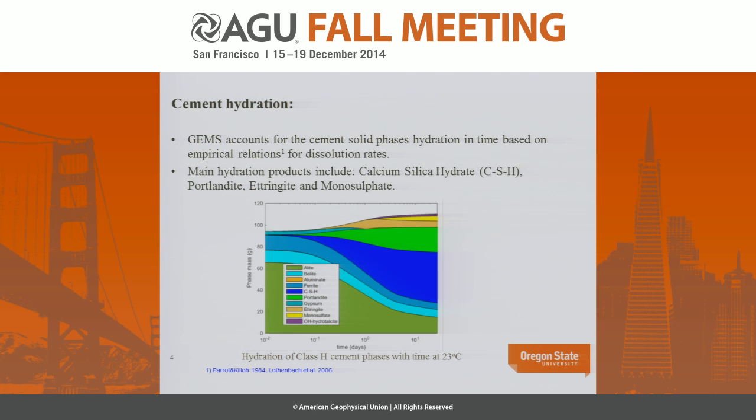Cement generally has 4 main phases, including C3S, C2S, C4AF, and C3A. This special type of cement that we use has a very low amount of C3A, which results in a very low hydration rate and a very low amount of cracks, which is very suitable for the wellbore system.